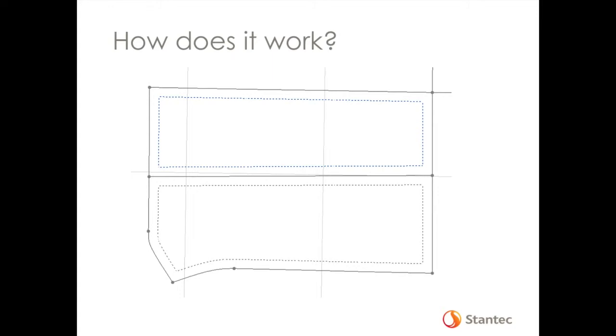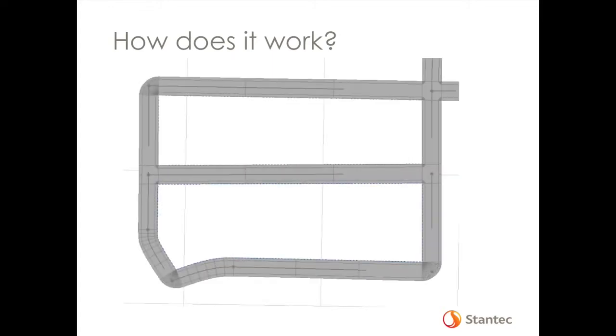Once it creates a closed shape, it actually detects now that it's a closed parcel, and it'll actually create another little blue line. So it's going to start subdividing parcels as soon as they're interconnected. Next step is we actually want to tell the center lines that it's a road. This is just as simple as dragging a rule onto that object, and it turns it into a road. Doesn't look like much yet.